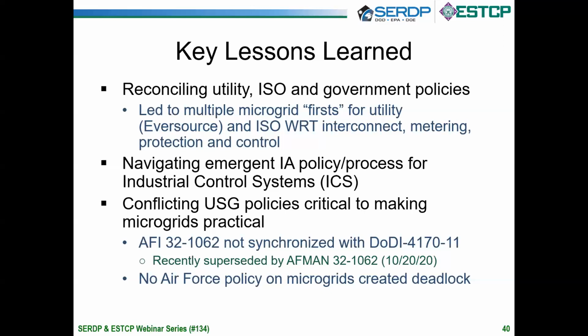And there was a competing Department of Defense instruction that basically said, we encourage you to do the exact opposite and use your generators to support loads as broadly as you can, and use existing distributed energy resources. So those two particular instructions, one being Air Force, one being DoD wide, were not well synchronized at all. And ultimately in the project, what that ended up doing to us was we couldn't use that generator to island the system towards the end of the project, which was really a shame.